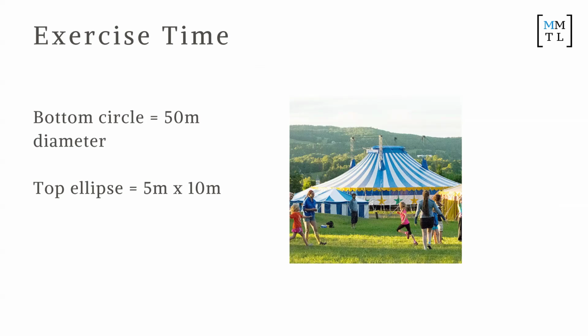So offset plane just means that you have this initial plane, the origin, original plane, and you want to do something on top of that, so you need to do some offset, because it doesn't know where you want to operate. How do I offset that? Oh, so you have to project. Just think about projection, like a circle. Then you click the bottom one, click the top one. But you don't need to project anywhere in this case, because we're not using a circle.